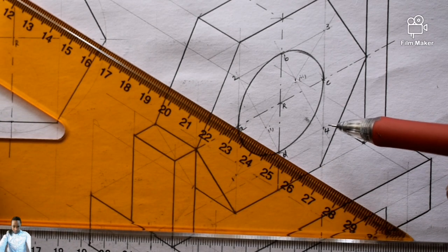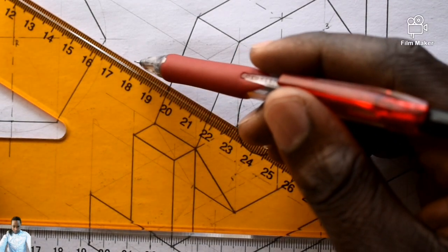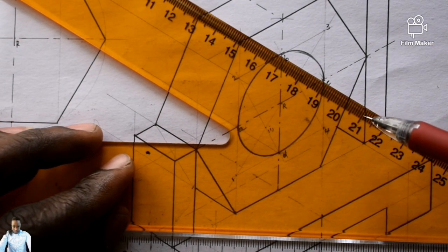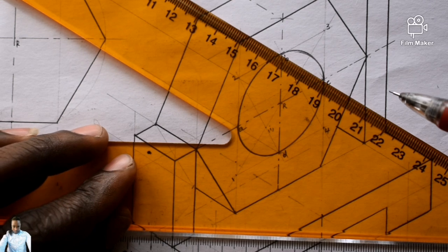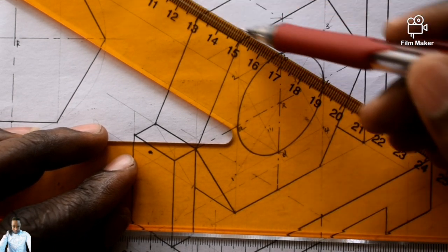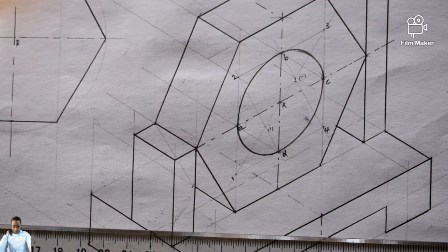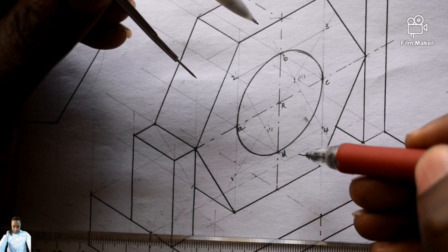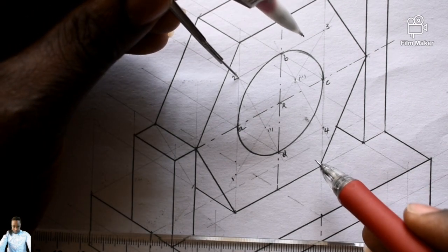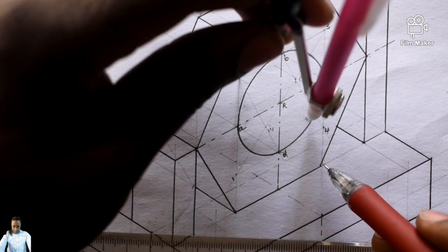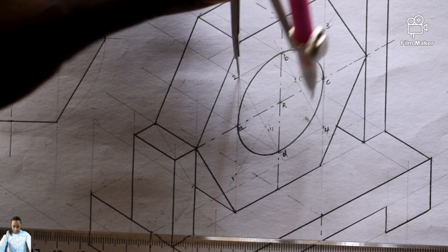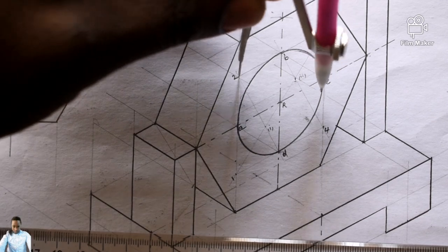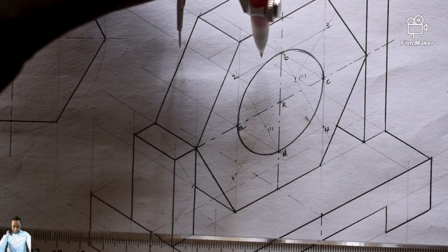So I'm going to take point D a little bit back as well, faint, point C a little bit faint as well. So now I come and record, okay, I drew this arc of CD by placing my drawing compass at point 2. That's how we drew it, isn't it? So now without disturbing my drawing compass, I'm going to place it along this line.